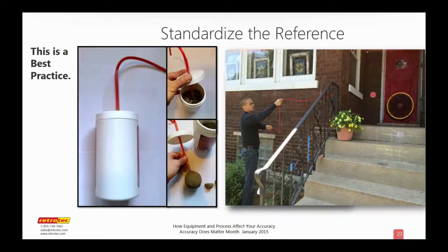So sorry about that. Point is that if your manometer or your gauge, whichever kind of gauge you're using, is on the ground, or if you have a tube that sticks out of your input and it's laying here in front of this fan, it can cause air to move across that tap, that port, or that tube, and that can really skew your results. Thanks a lot, Joe. So last thing I just want to mention is just make sure that when this frame is installed that it fits snugly. That can actually cause problems, and especially in the tighter houses, your results can also vary greatly.